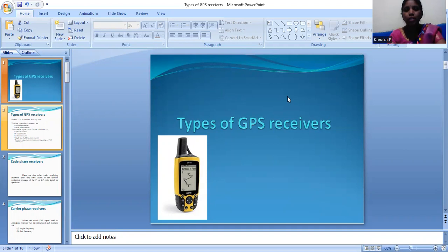Next is the segments of GPS. GPS is comprised of three segments. The first one is the space segment or satellite constellation, the second one is the operational control segment or ground control or monitoring network, and the third one is the user equipment segment or user receiving equipment. That is 6 planes and 55-degree inclination. In the space segment, a total of 24 satellites make up the GPS.